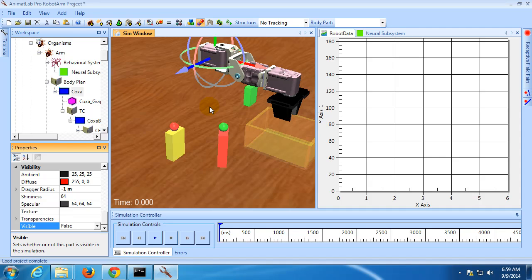All the parts we will be using to build the robot are from commercial, off-the-shelf robotics components. For the frame, I'm using the standard Bioloid frame kit. The motors are Dynamixel AX-12 servo motors. The gripper was a kit purchased from Robotics. The pressure sensor we'll be using was also purchased from there. In this tutorial, we'll be using an Arbotix Arduino board to control the movement of the arm and get input from the contact sensor. The Arbotix is a special Arduino board available from Robotics that allows you to control Dynamixel servo motors. Dynamixel servos are some of the most widely used servos in robotics.